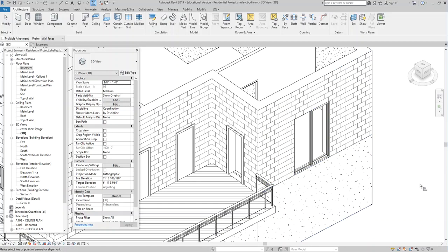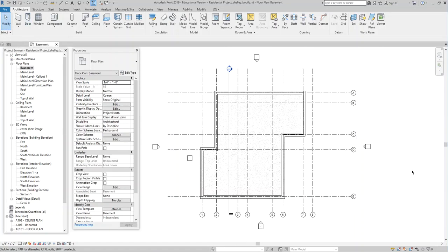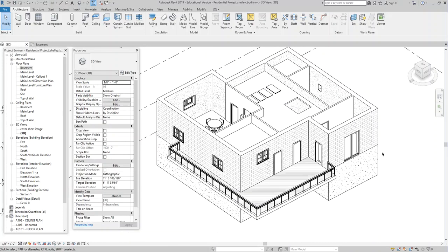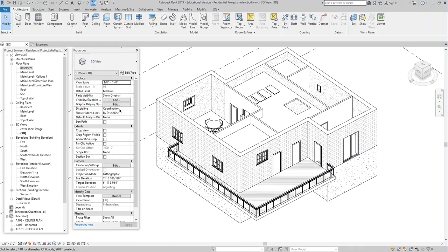Yeah, do that all the way around. It will align it all. So as you saw, it kind of worked out for me, but sometimes you're just so excited when things work out, right? You have to watch the top and bottom constraint. It toggled for me for whatever weird reason. When I changed the alignment, it toggled and the wall was going the wrong direction. So make sure you pay attention to the alignment.